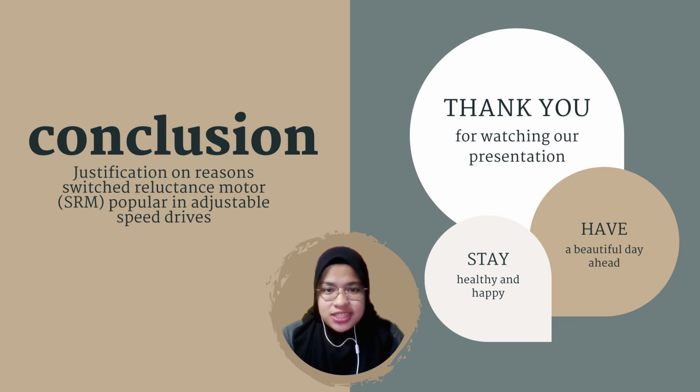So, from the question, justify why the switched reluctance motor SRM is popular in adjustable speed drives, we can conclude that the switched reluctance motor, or SRM, is popular because of its simple structure, its robustness in harsh conditions, and because SRMs are cost effective. That's all from me and my group mates from Group 1.